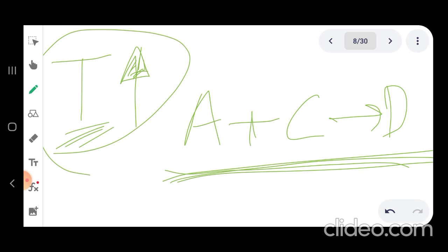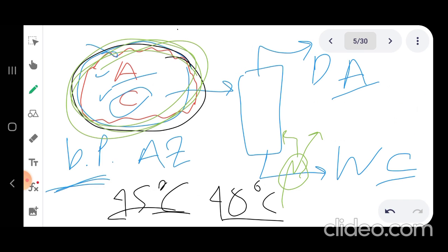So this is bad. You are losing your components, and you are forming this third component that maybe you don't need. You don't want it. So in this case, separation by distillation is not good, and you need to look for an alternative process. This is just an example of typical reasons to go for another separation technique rather than the most fundamental, famous separation technique, which is distillation.